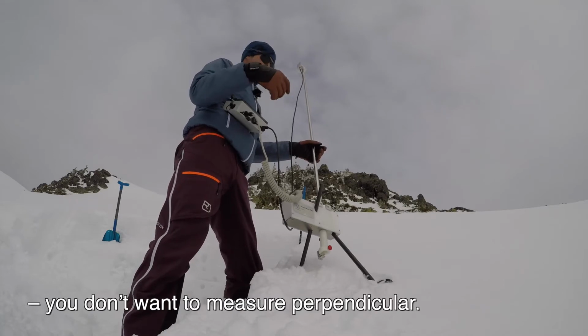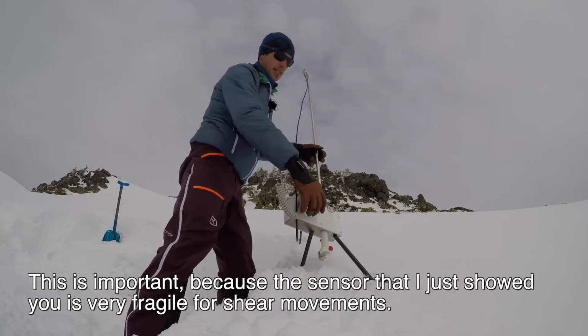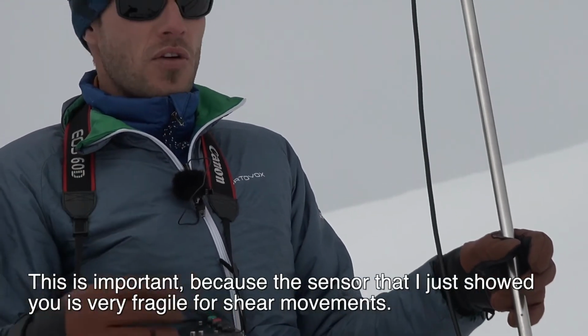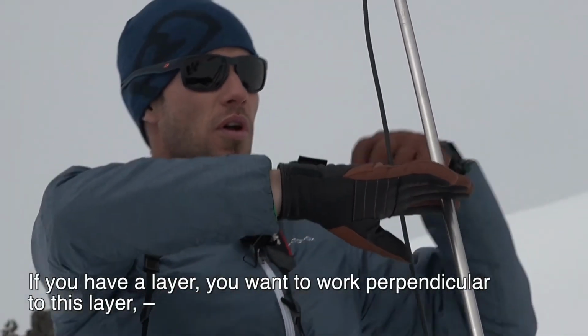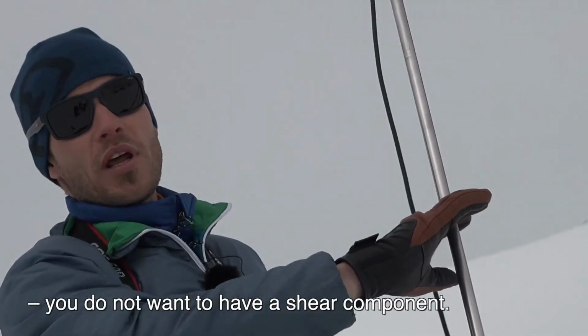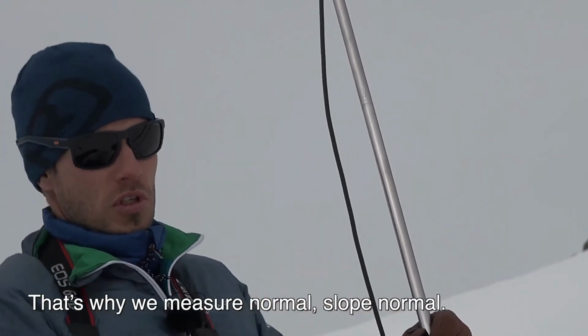You don't want to measure perpendicular. And this is important because the sensor that I just showed you is very fragile for shear movements. So if you have a layer, you want to work perpendicular to this layer and you don't want to have a shear component. That's why we measure slope normal.